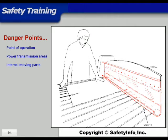Dangerous moving parts are found in 3 places: the point of operation, power transmission areas, and internal moving parts. The point of operation is the point where machine force is exerted on materials for operations such as cutting, shaping, boring, or forming. Power transmission apparatus are shafts, belts, chains, pulleys, cams, connecting rods, and other parts that transmit power from a motor to parts of the machinery.